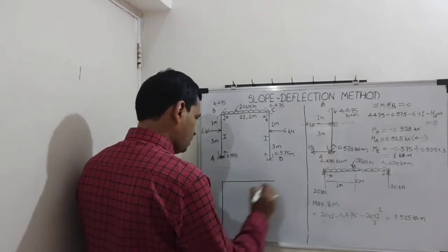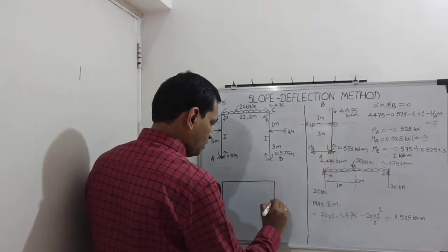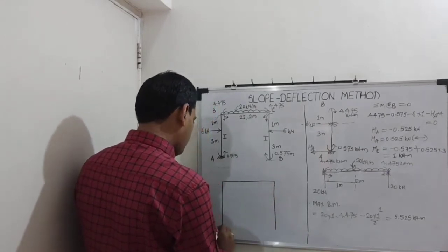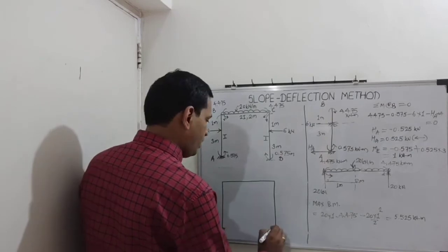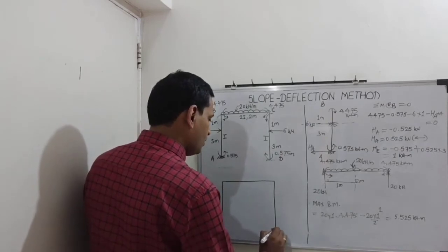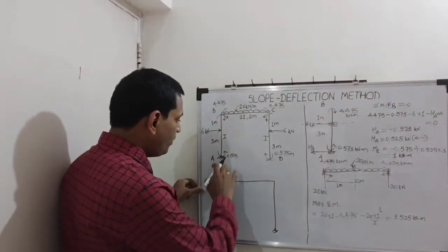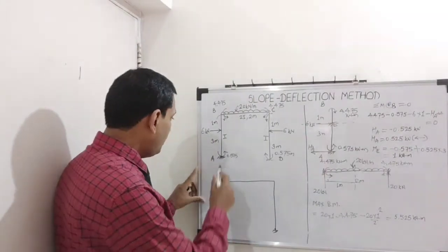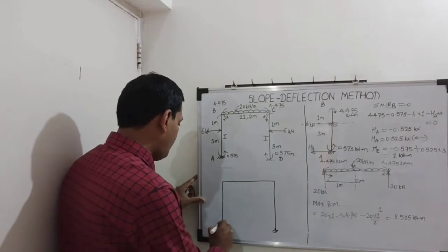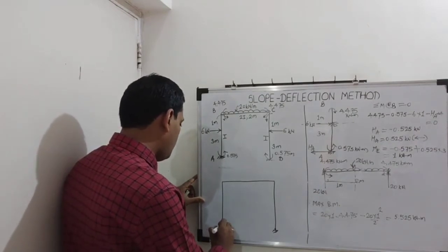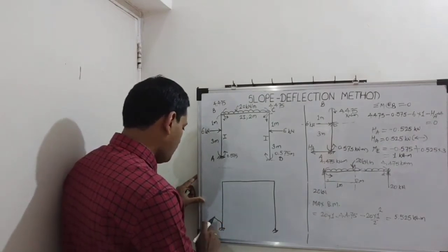One thing I will do is, I will first of all draw the deformed shape of the frame here, and as per the deformed shape I will draw BMD here. So anti-clockwise moment on joint A, so it is going to deform column on left hand side, so it is something like this. Okay.